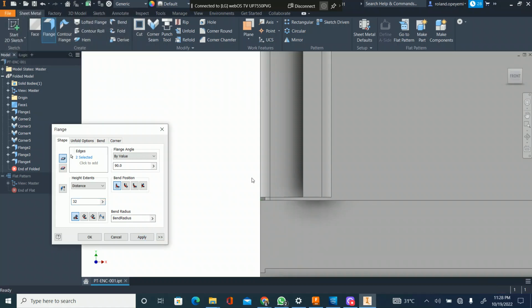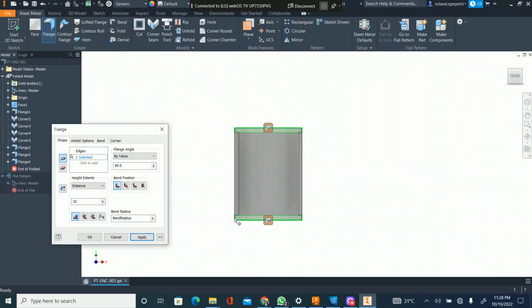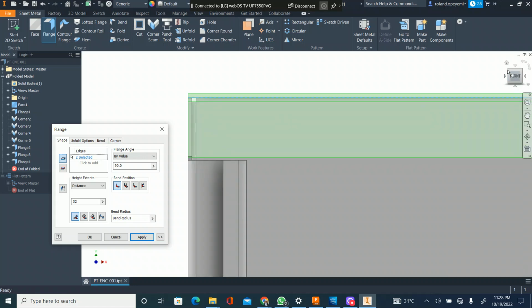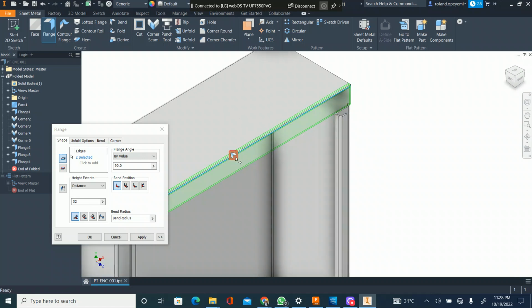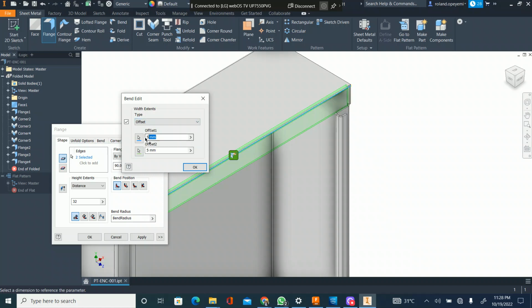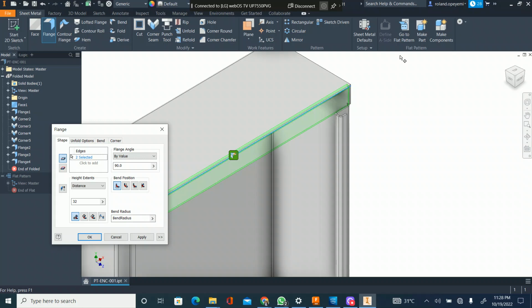So another thing you want to be careful of is this kind of thing here too. See, this edge clashes at this point, so you want to make sure you have a good backup. So for here you can do the thickness of the sheet plus 0.5. As the sheet thickness is 2, you type thickness, because it's already the default, plus 1. You understand? Setting that part straight.